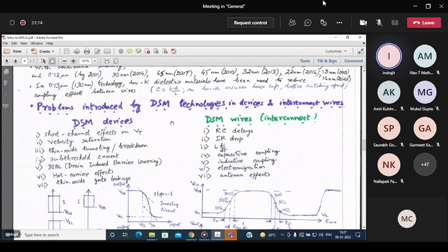They tend to pass from the source island towards the drain island through the channel. And while they are progressing, they are traveling at a certain speed. That speed cannot go up indiscriminately. The carriers attain a saturated or maximum velocity beyond which they cannot go.